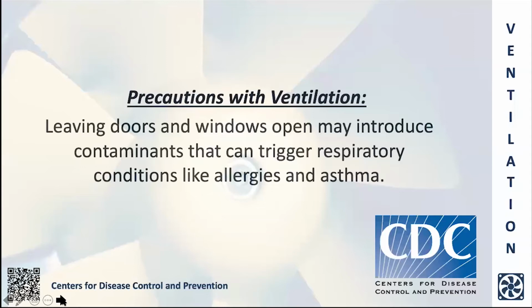So leaving doors and windows open, or again, increasing the amount of outdoor ventilation, if not filtered properly, we can introduce other problems like allergies and asthma, or triggers that cause those problems to become much worse. One of the other things that we have to remember too, especially in a school environment, is that by leaving windows and doors open, we also leave ourselves open to noise pollution, to where we cannot get the same level of focus out of our teachers and students when we have all of that outside noise going on around them.